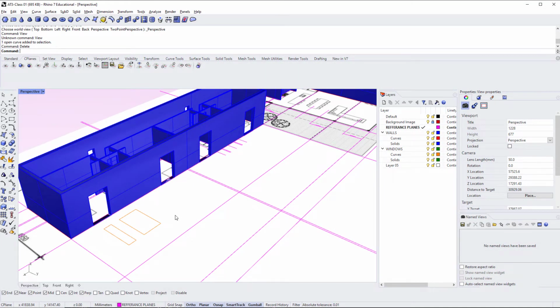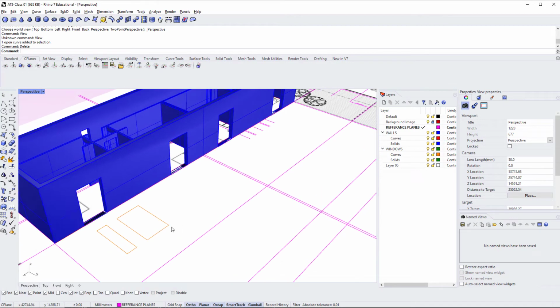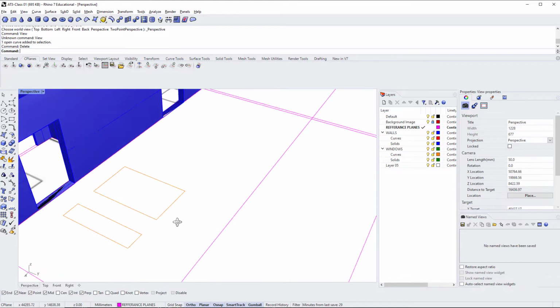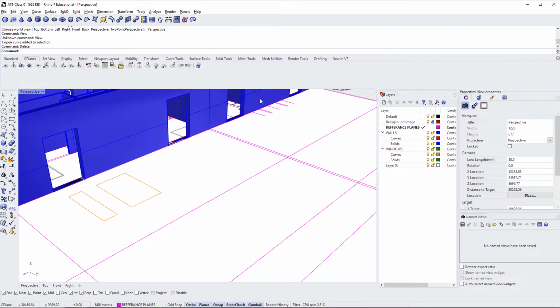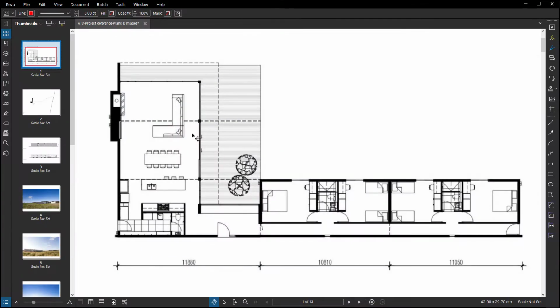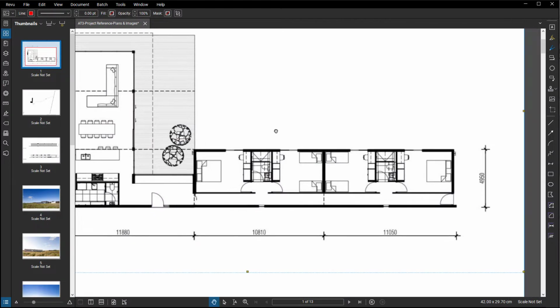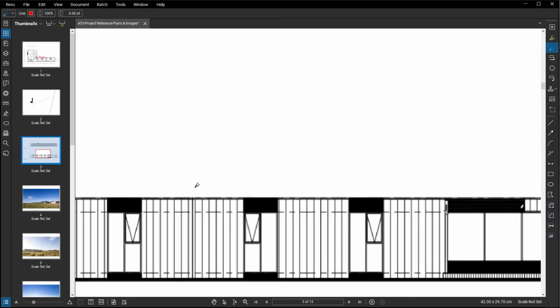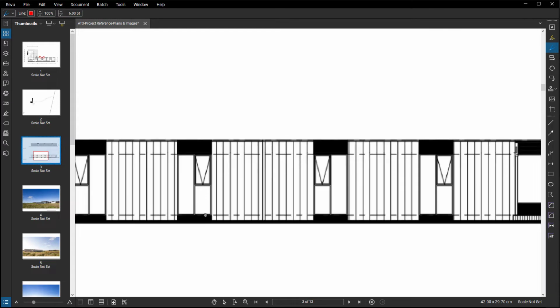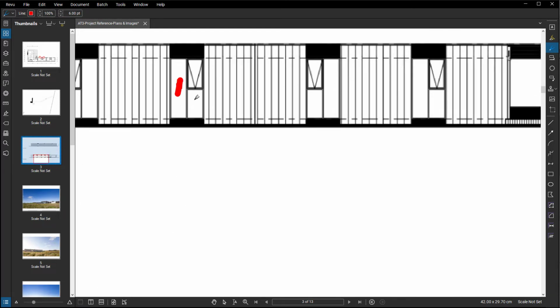With all the window and door openings now accounted for, let's take a quick look at blocks and how to utilize them. So we're going to begin with our standard awning window, fixed and awning windows, which are in each of the bedrooms. So it's 1 block for 4 windows. And if we look at the reference images on Student Web, we're talking about these windows just here. Now if we go to the elevation, we can see its typical design is 1 fixed pane, another fixed pane, and then our awning component just here.